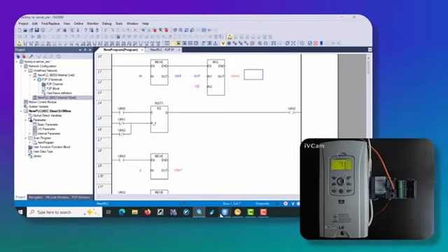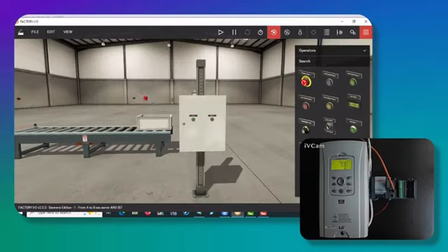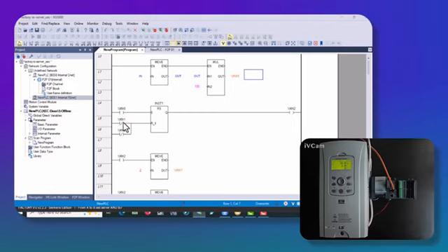MX2 is the same value that I entered here in the factory I/O software, which means address 0. I set it to start from MX2. Okay, I connected my output to MX2. Start is on MX0, MX1 is stop, my sensor is MX2. And in the coil, MX2 is also set so they don't interfere with each other. If you select MX2 in your read area, there's no problem. And even if you select it in the write area, they won't have any issues or interference with each other. Okay.